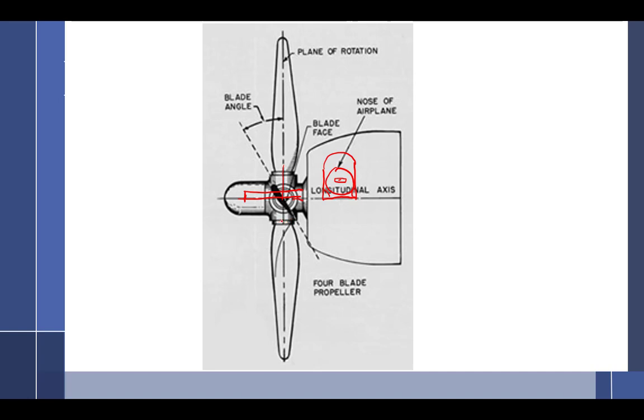Yes, Tim, the crankshaft. If I were to pull the prop off and I could put this right here on the crankshaft, is that going to be in line with the longitudinal axis? That's the number one answer. So pull the prop off. In fact, that's what I have you do now. I changed the project, and that teaches you two things: one, how to get a really good longitudinal axis, and two, how to take a prop off and on, and why you need a bucket.